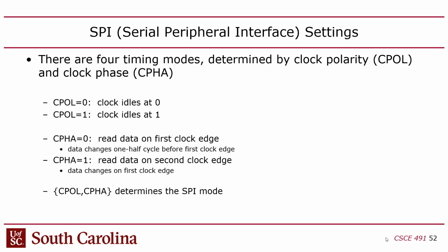Now, another thing is, and this is the one that's a bit more confusing. So you guys remember from 611, and hopefully you covered this in 311, when you have a clock in a digital circuit, generally you're using the edge of the clock, right? You're triggering things on the edge. The flip-flops read on the edge of the clock. They're edge triggered, right? Make sense? Now, level triggered would be like a latch. Edge triggered would be a flip-flop, but everyone uses flip-flops, right? Latches are fairly rare in digital circuits, right?